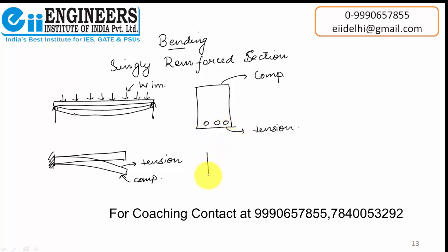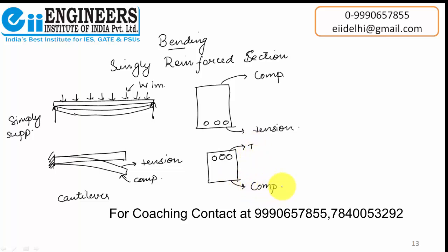But in the cantilever case, we provide main reinforcement on top, because top is in tension and bottom is in compression. Here we provide bars to resist tension.